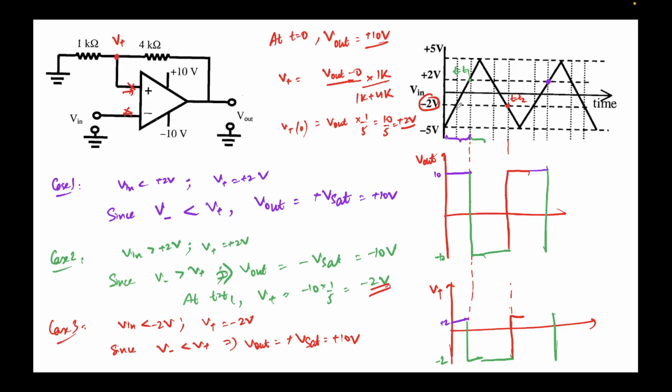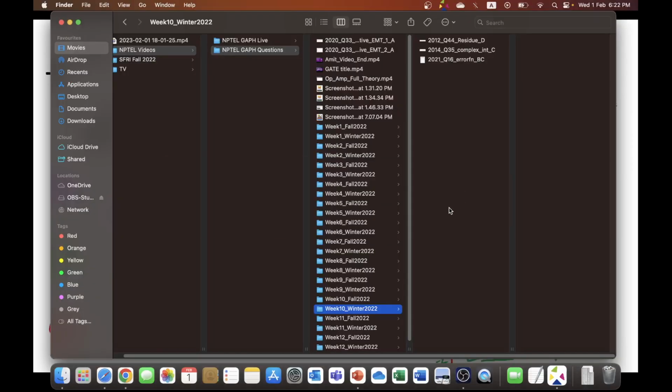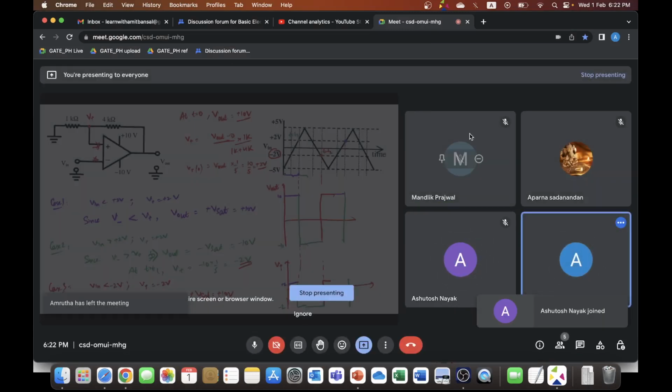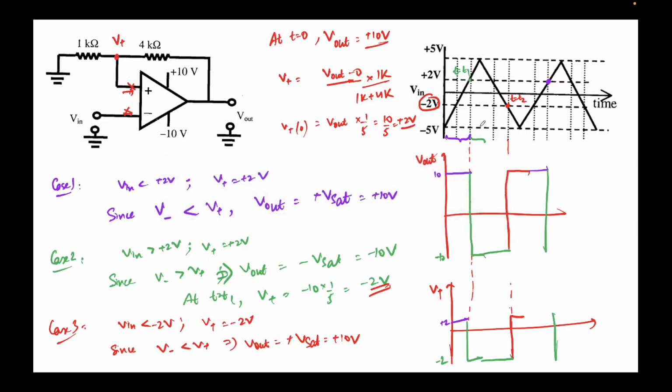When the input voltage is rising, the corresponding reference voltage was plus 2 volts, as you can see over here. However, on the falling edge, the reference voltage was minus 2 volts, and so the trigger points were different. This is sometimes referred to as hysteresis, because the rising edge and the falling edge have different threshold voltages. Keep this in mind, because there are different forms of this question usually asked. You may want to recall that the threshold voltages are different, and different terms are used.